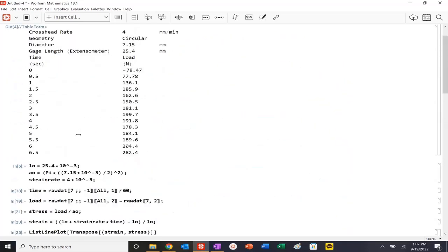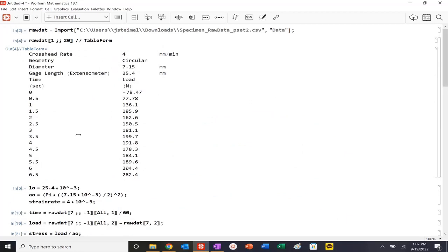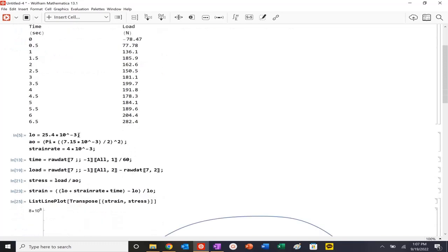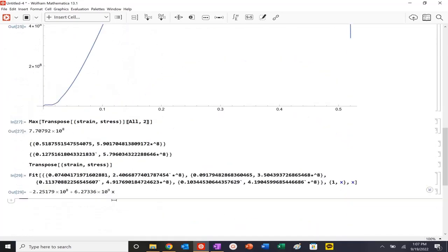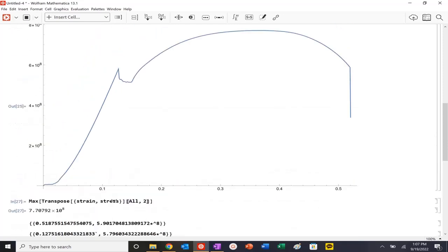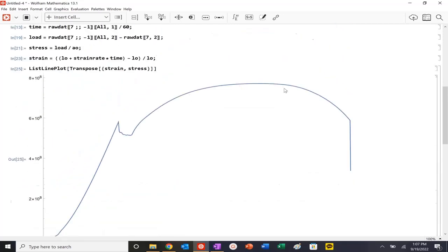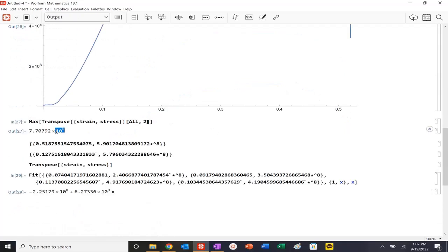So we plotted our engineering stress strain curve. We've basically measured a bunch of values here. We were able to do that quite easily, quite successfully, using Mathematica. So we've got a lot of these values. We can see now we have an estimate on what the material we're working with probably is. So maybe some type of very brittle polymer and a relatively stiff polymer as well.